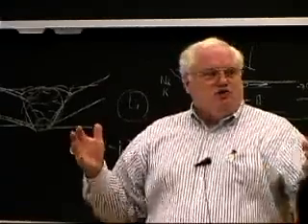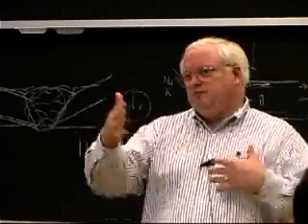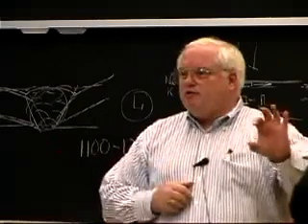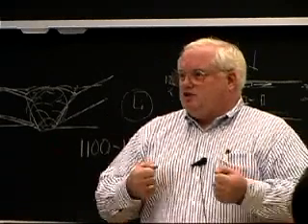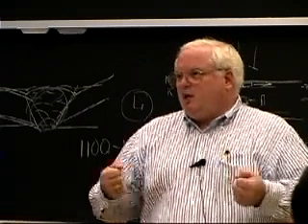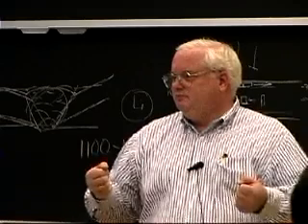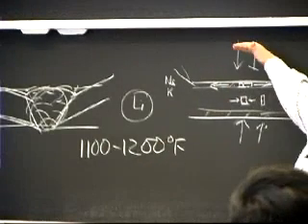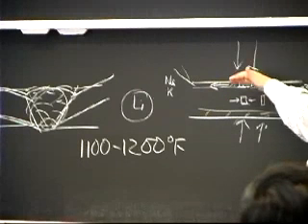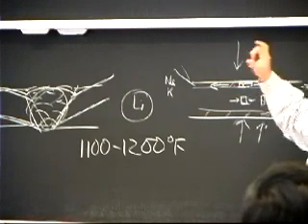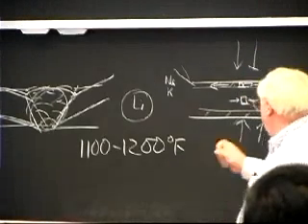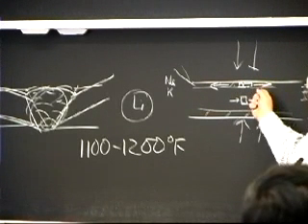And they have a huge machine, both sides of it are about the size of this room, and it can grab a plate 3 or 4 inches thick after it's been heat treated, and they stretch it 1 to 3%. Because the heat treating process for aluminum requires that you heat it up and then quench it and then temper it. And that whole quenching process in a thick plate does the same thing it does to the glass, except, yeah, it may be compressive on the surface, but it's tensile in here.